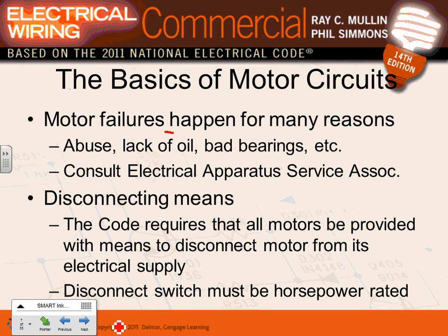Motor failures. Why do we care about motor failures? You don't have heat if the air handling unit stops working. Do you have heat and cooling in your building? No. So here are a couple of things that contribute to it. Abuse, lack of oil, bad bearings are notoriously famous for making your motor fail. Who cares as a designer? Really nobody. As a project manager in a plant, or an electrician troubleshooting it, that's a big deal. So you walk up to a motor, the motor is not working. How about, have we oiled that thing for the last 15 years?